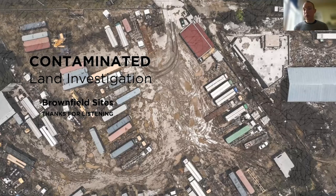On some sites you will sample in a grid, but on other sites you may try and keep your sampling locations within 20 meters of each other, but focus on those sources of contamination that you'd identified in the phase 1 report. So if, for example, you have tanks dotted randomly about the site, rather than having a grid that misses those tanks, you would focus on those tanks and then take untargeted samples elsewhere on the site to give you a comparison to work with.